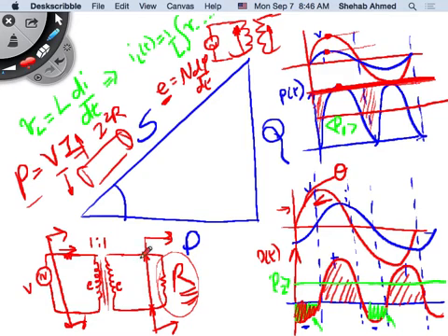So if some of these turns of the transformer are shorted, am I going to have some voltage or not? I will have, but this will also cause the current coming in to be higher. So the magnetizing current will become higher. At some point, maybe my power supply at the input cannot cope. That's a different story, right?